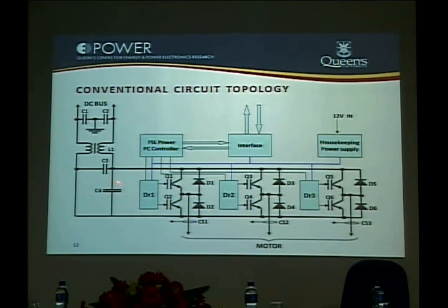Also, in order to increase the reliability of the inverter, because this inverter has to work for at least 10 to 20 years, this is not an electrolytic capacitor. This is a polypropylene high frequency type of capacitor. And this capacitor is quite expensive; the cost of this capacitor is almost 60% of the cost of this module. So this is a very, very expensive capacitor.